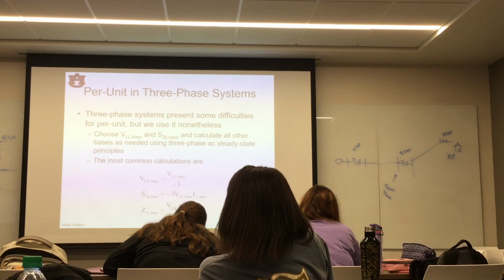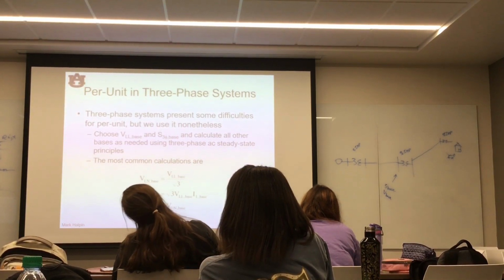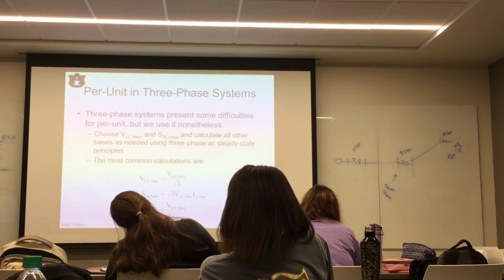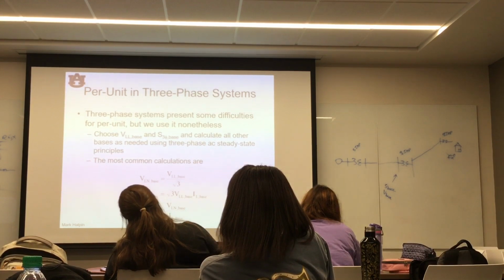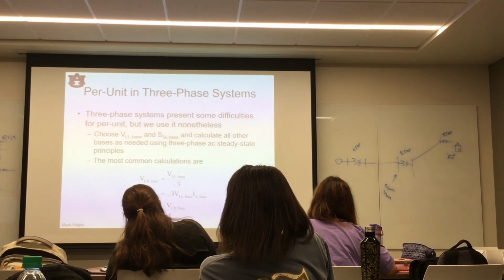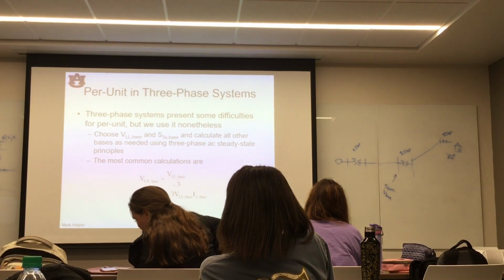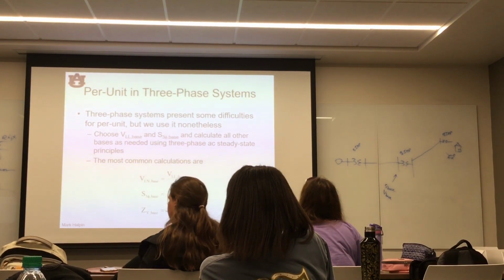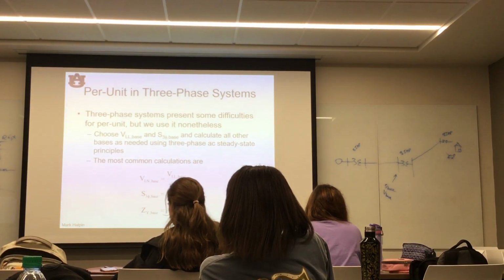The issue is what power, okay? Because in three-phase applications, I can talk about picking the power in one phase, or what we might call the single-phase power, or I could pick the three-phase power. What do you want to pick? Well, you could pick either one. We customarily pick the three-phase power. We don't pick watts, we don't pick volt amperes reactive or vars, we pick volt amperes, period.